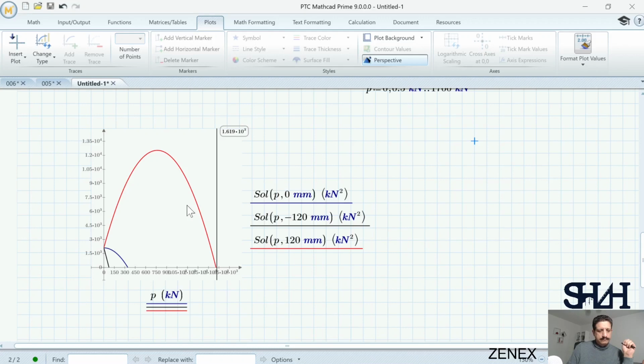In FEM software, for example, in RFEM, when we are adjusting the setup, there are three options: the load is in the shear center, the load is below, or it's above. When it's below, it is written that this is a stabilizing situation.